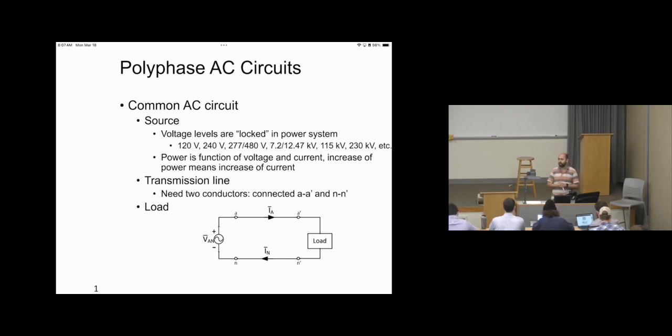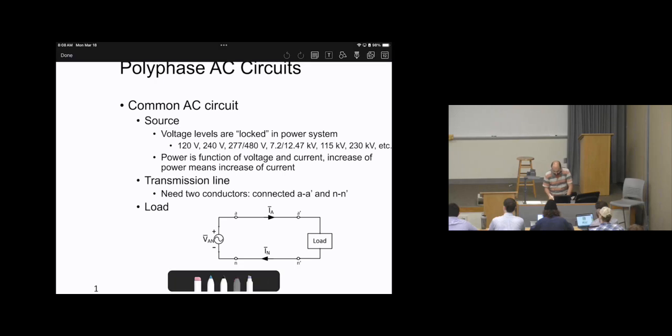So when we go to the power lines, if you know the type of power line, then you know what the voltage is, for example, 132 kilovolts. What we don't know is the current. Why don't we know it? Because the current depends on the load. We know the relationship for power: S bar equals V bar times I bar conjugate, right? So V is constant, and we will realize that S bar is directly proportional to the current. Let's talk about the magnitude.